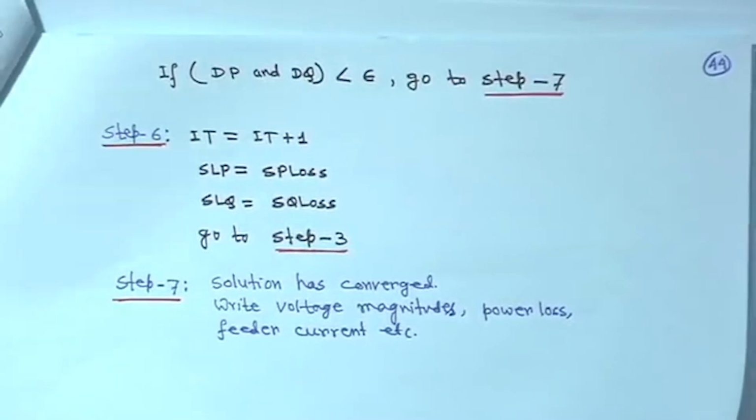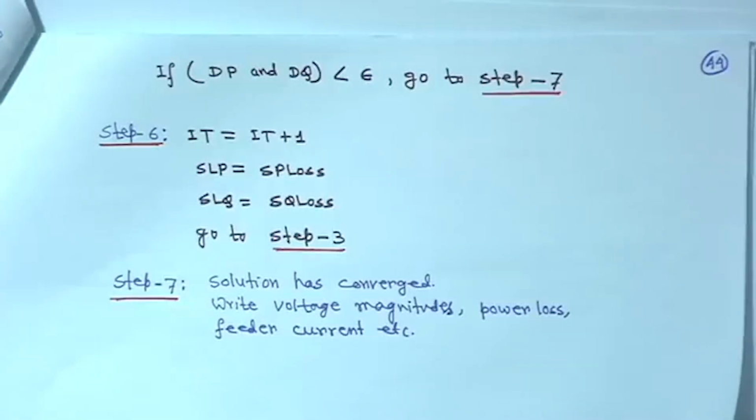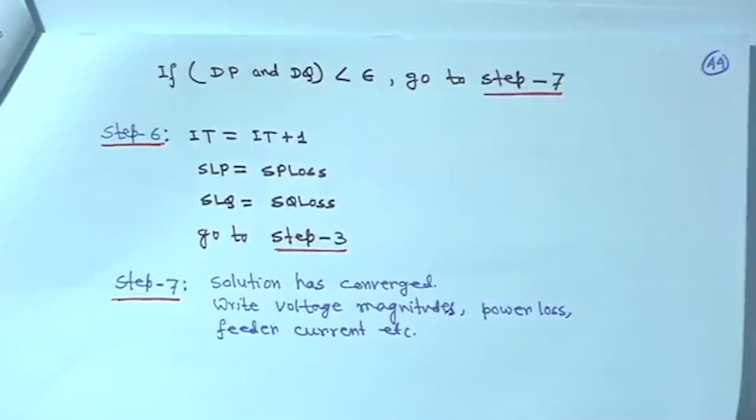Actually, the network is radial, and its radiality structure has been exploited to form such algorithms. But if you want to solve the same radial network using the Newton-Raphson method, that also can be solved, but the recommendation is that you use the coupled Newton-Raphson method. Decoupled and fast decoupled will never converge, because you will find that these radial networks are very weak. One branch is coming in, and maybe one or two branches are leaving.